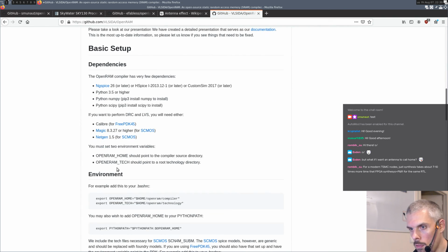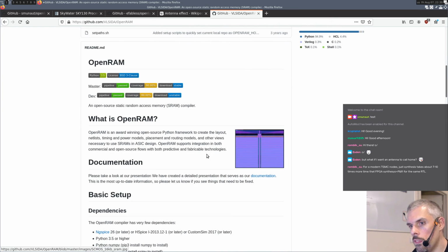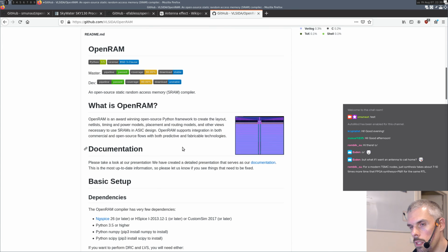There are a couple of issues with that. The first one is that in your register file, what you want, at least for a common RISC-V design, is two read ports so that you can read the two register arguments at the same time in the same cycle, so you don't lose a cycle just to read arguments out of it.